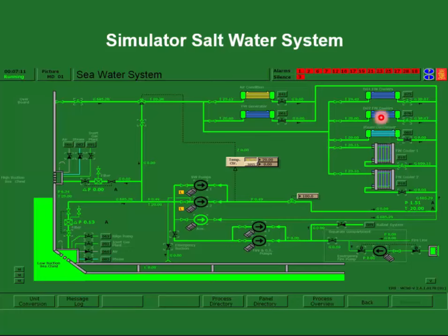They're only showing one heat exchanger here, but these are for SSDG number 1 and number 2, and they actually have multiple heat exchangers in those rooms, saltwater to freshwater exchangers. Then you also have a distiller, saltwater heat exchanger, and an air conditioning heat exchanger. This is your overboard. This again is your 3-way valve and circulating back to the suction of the pumps.